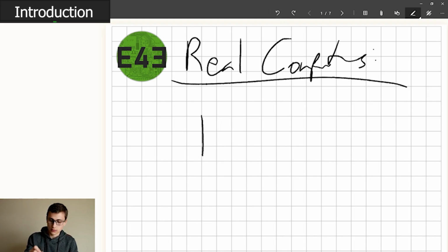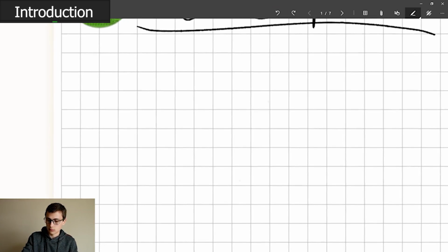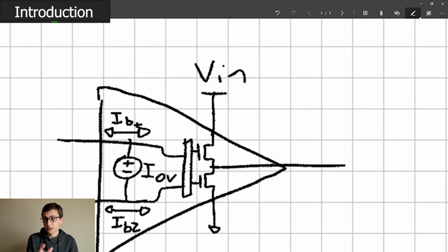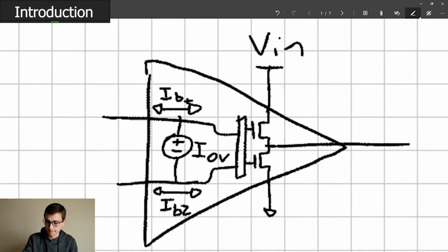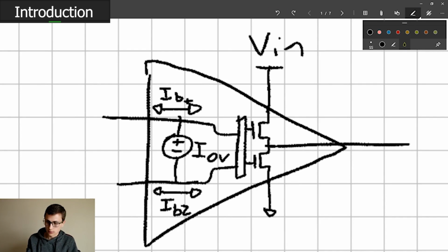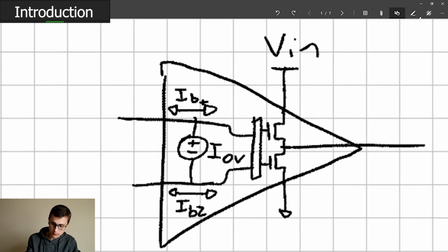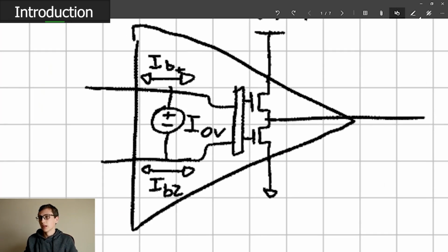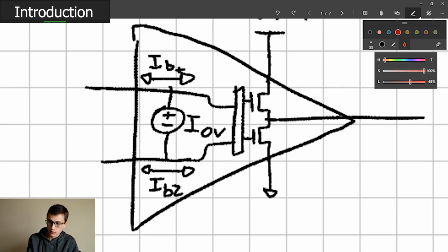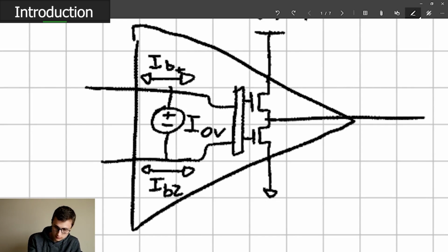But basically, we're going to draw one of these guys real big. So you can see it's kind of simplified. Basically, I'm showing that we've got an input voltage that's got a push-pull output stage. You know what? That input offset voltage, it's really not drawn right. So if I really wanted to draw that input offset voltage more accurately, I would need to put it in series here.